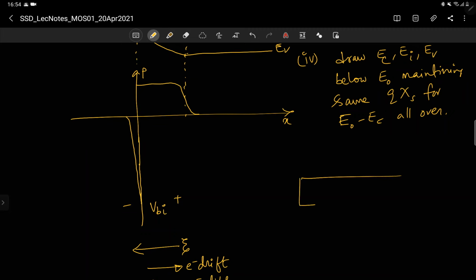So for any metal semiconductor junction you take, if you mark the semiconductor as plus and the metal as minus, then the built-in potential you can simply write as phi ms. So phi ms you write as the contact potential of a metal semiconductor junction. Always remember the signs, because contact potential, for a PN junction, you know, is given by VT ln (Na Nd / ni squared). Fine. But which side is positive, which side is negative? There you remember that the n side will have donor charges, so the n side should be positive because that is positive charge.